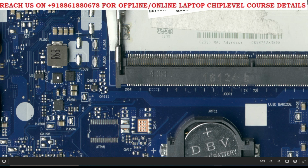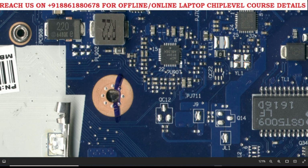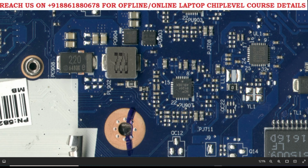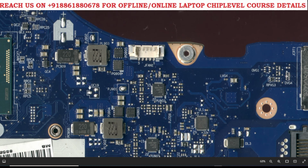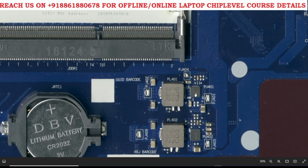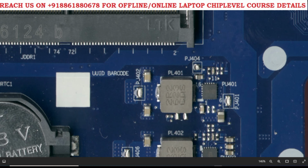The thing is, these two MOSFETs are controlled by this IC through the gate. One more here: this IC will control these two MOSFETs and give the appropriate output, like 5 volts. Here, just an example I am giving, not the exact one. So this IC will control these high and low MOSFETs and give the appropriate output, say 1.2 or something. In some cases only the IC will receive the direct 19.5 volts and give the appropriate output at the coil